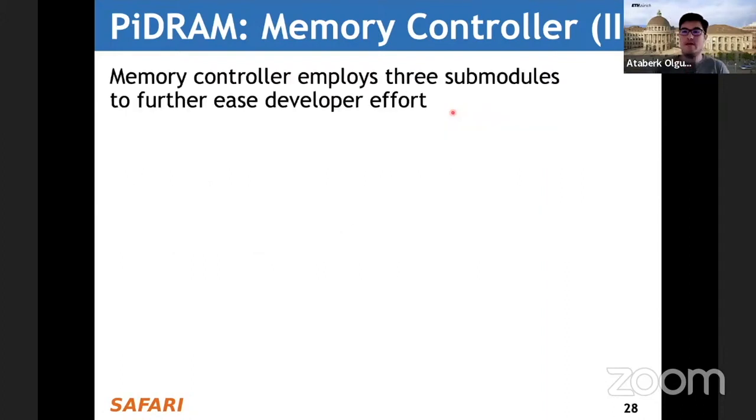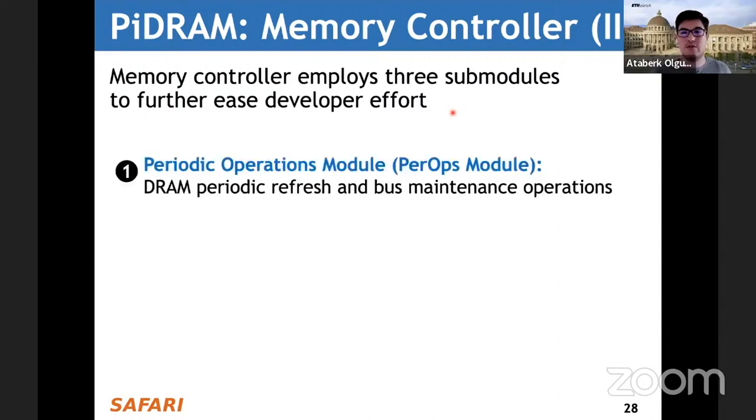And we implement 3 submodules to further ease this effort of integrating new stuff and using the platform essentially for development purposes. And the first one is the periodic operations module, which performs periodic refresh and bus maintenance operations to keep the DRAM bus in a valid state, and the DRAM cells refreshed.